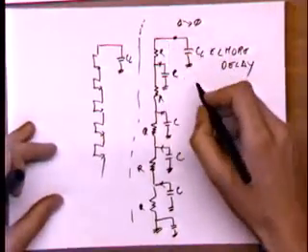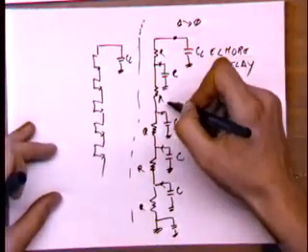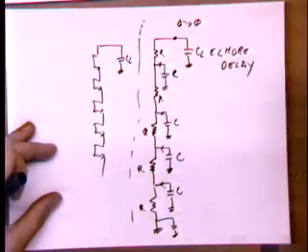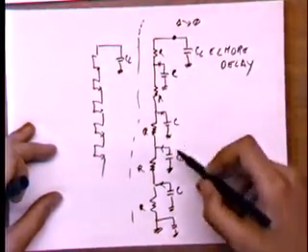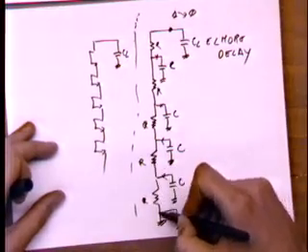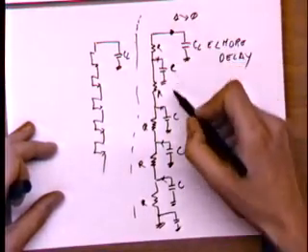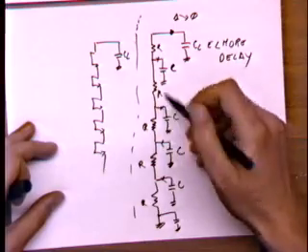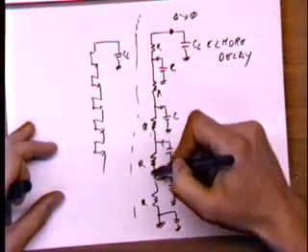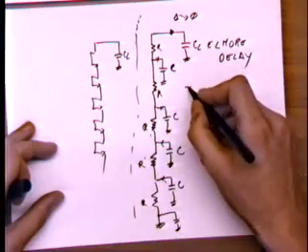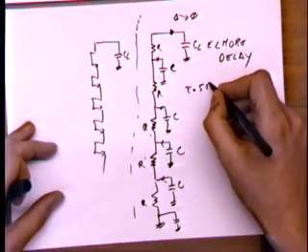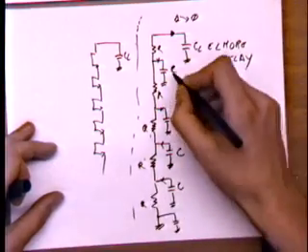and then you take a first time constant, right? So you walk from the output back towards the input. In this case, you walk from here towards ground. So you take this first capacitor, you ignore all other capacitors, you look at what's the equivalent resistance in, which is 1, 2, 3, 5R. And you say, okay, my first tau is 5R CL, okay?